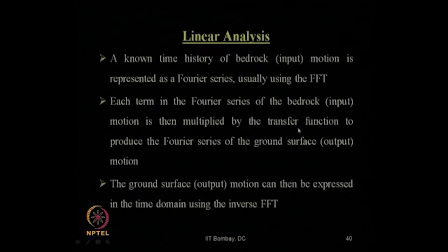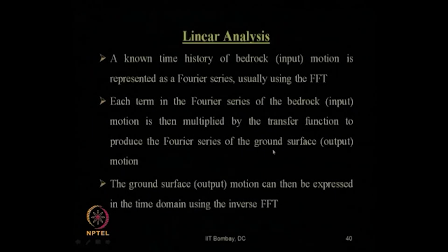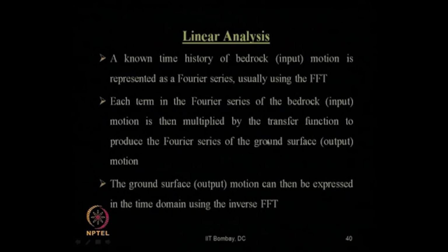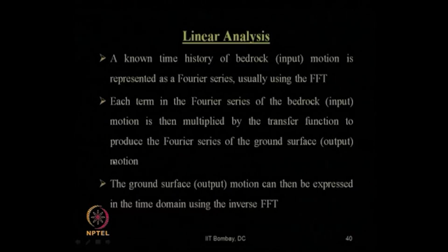It is nothing but a multiplier, a factor by which we multiply this input motion so that it produces the Fourier series at the ground surface, the output motion, that is the free motion. If we do not know the free surface motion, then from the bedrock motion we can get it like this.